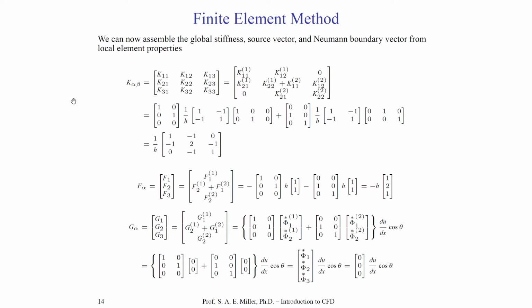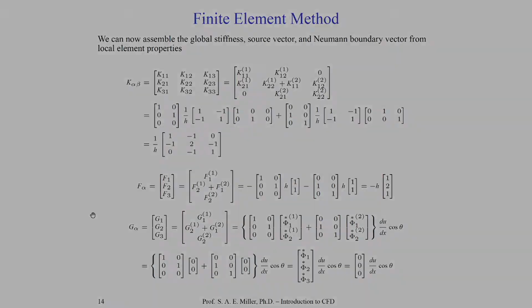If you want to write your own finite element solver, I strongly encourage you to try the one-dimensional problem first for simple compressible equations. Then you can extend it to 2 and then 3 dimensions. It's really the only way to do it, and it's very difficult to write a fully 3-dimensional solver without practicing the one-dimensional case first. That's just good advice for new people to CFD who really want to learn how to do this. I encourage you to try the one-dimensional formulation yourself and try and recover some of these coefficients.